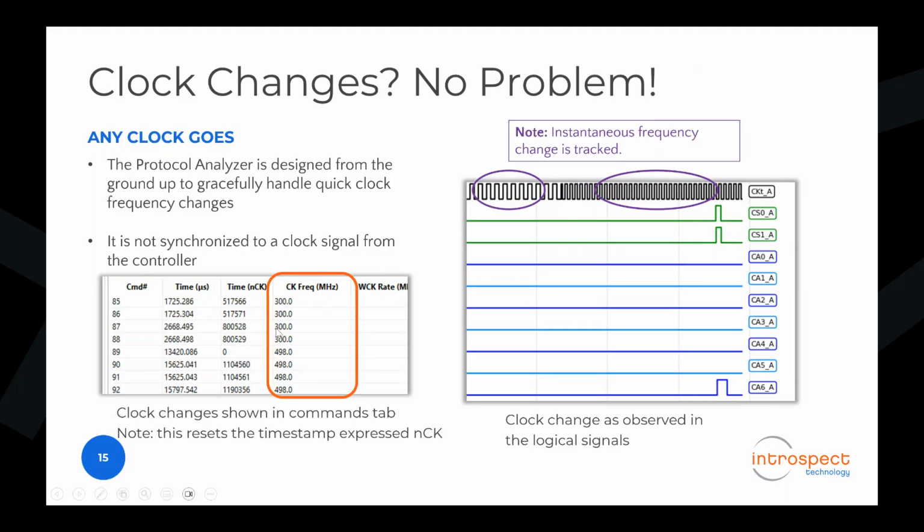And so here in the human readable table, you can see that the CA bus was running at 600 megabits per second initially, and then it flipped to about 1 gigabit per second for the CA bus, right? And so these are just the FS frequency set points that the LPDDR spec specifies essentially, and this particular boot up sequence is showing us that the phone had gone from cold boot to the first frequency set point, second frequency set point, and so on.